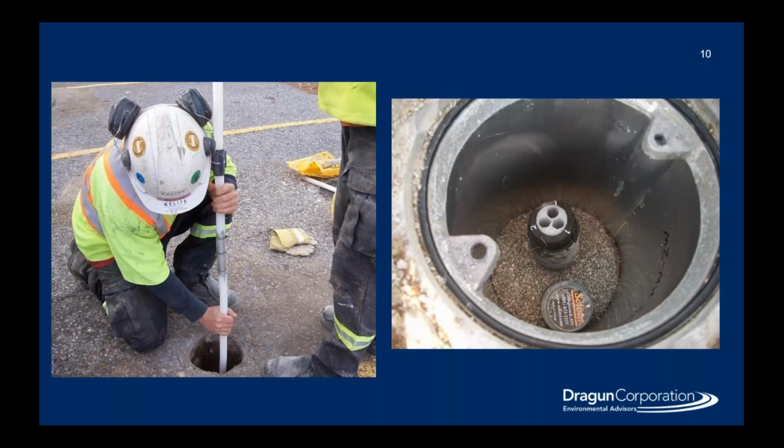And here you can see them actually installing the tubing within a borehole. They typically have a centralizer to keep the tubing in the center of the borehole, and as it's being installed, you have to be careful to make sure you get an effective seal between the screens, so that there'll be sand put around the screens to allow for the water to enter the screens. But between the screens, we don't want vertical communication between the areas. So we put a bentonite seal or something that's impermeable between the screens within the borehole to make sure they're isolated from each other.